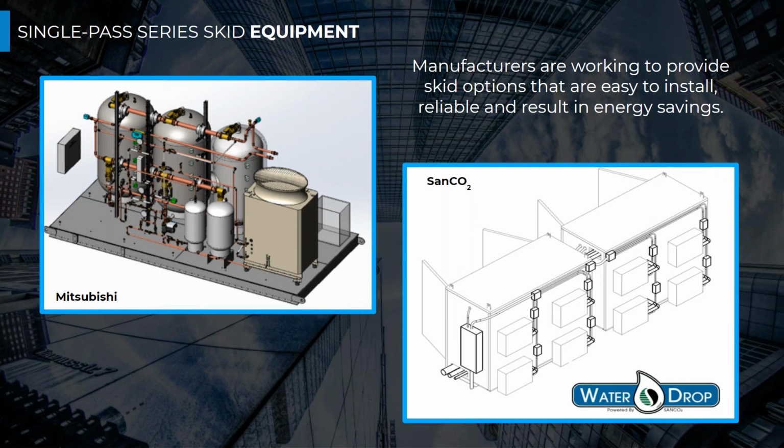Got it. Yeah, I'll just do one more here. Someone's asking, with the R134A, how much of a difference is there in efficiency with a 90-degree lift versus a 10-degree lift, and basically which one of those is more efficient? Yeah, typically the 90-degree lift is more efficient. It's allowing the heat pump to use its full heat pump cycle, essentially, or capture more of that free heat available through the ambient air.